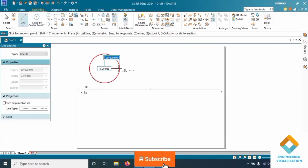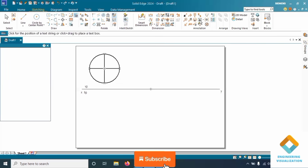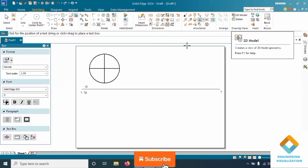Here I'll be constructing a circle using the center method. So for the diameter we'll take directly the major axis dimension. In the question the major axis is 60 mm, that means we'll take the same diameter, that is 60.